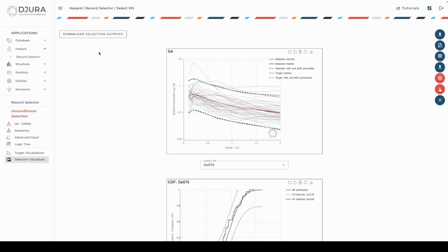So that's basically it. Here we've looked at a simple and fast ground motion selection based on the unconditional spectra for given IMs, selected ground motion models, and rupture scenarios. This can be used to identify the shaking for a given rupture scenario, knowing that the distribution of IMs for ground motion and intensity measures are going to be selected and represented consistent with what well-known ground motion models will be predicting for those rupture scenarios. Okay, so we've tested this. We can see it works quite well.